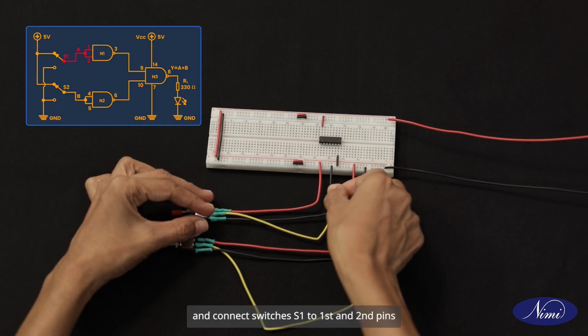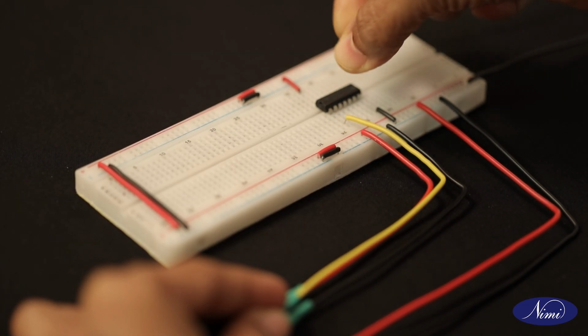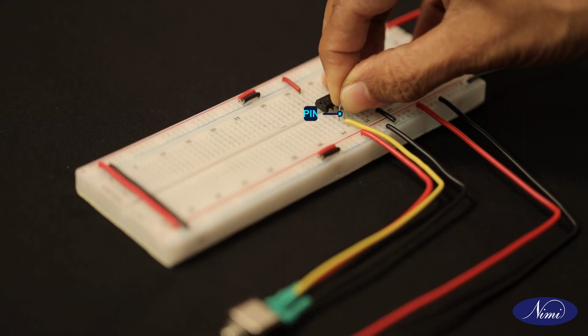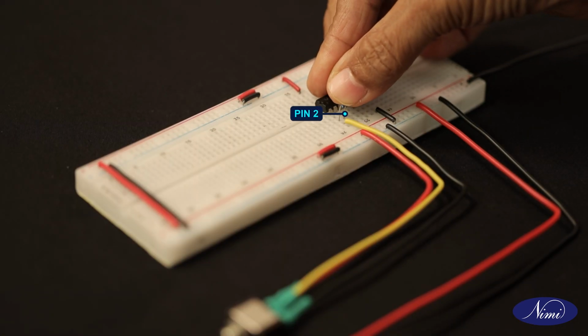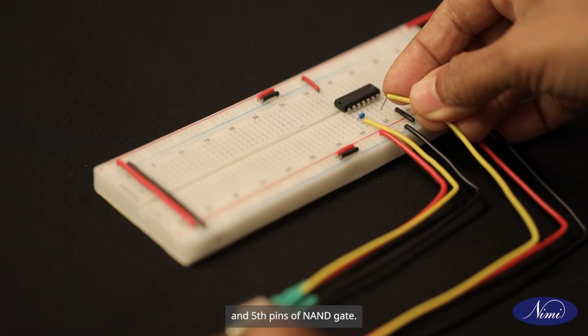And connect switches S1 to the first and second pins and S2 to the fourth and fifth pins of the NAND gate.